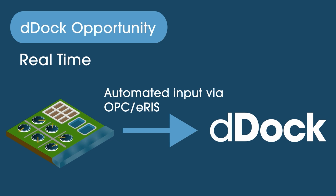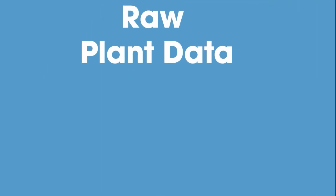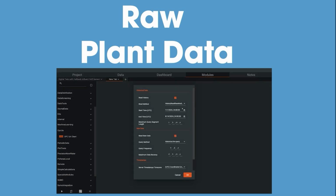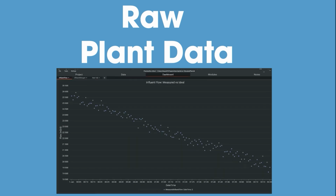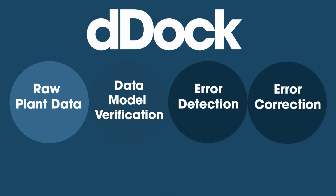By giving your team the power to customize how data is analyzed and presented, dDock puts real-time decision-making in your hands. How does dDock help you realize these benefits? dDock is a real-time analytics software package that can be linked directly to your plant's OPC or ERIS server. Simply drag an OPC client object onto the drawing board. Choose the appropriate settings for the data access method. Enter the node associated with the data to be accessed, and that's it. The data will now seamlessly be transferred to dDock for further analysis.